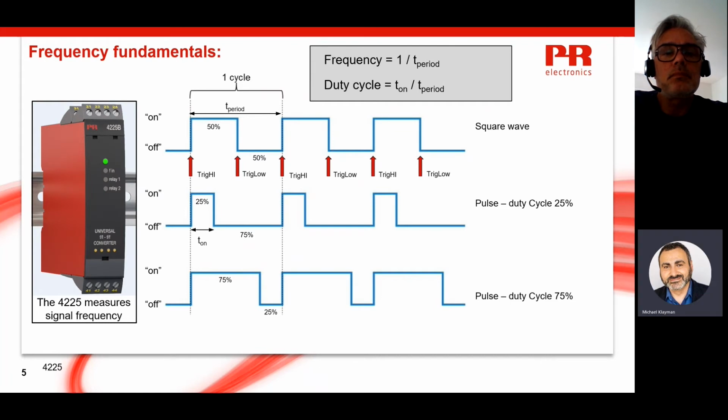The on-off alternating signal is detected by the frequency converter. If we define the on state as a signal level above a specific level, that level is defined as the high trigger level, since the signal triggers the on state as it exceeds that level. We can define a trigger low level the same way, the level which the signal has to come down past in order to register as an off state.